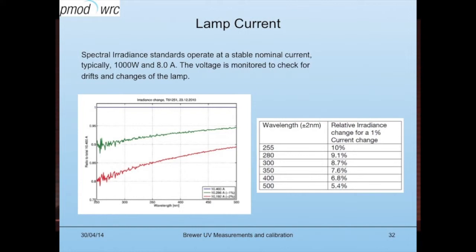For example, half of you have done the lamp calibration, and the company was really careful in adjusting or having you adjust the voltage for 12 volt, 0.000. And this is because the output of such a lamp is very sensitive to the power that it has. Now, usually when we operate lamps, we are controlling the current and not the voltage. Now, in the case of the 50-watt lamps, historically, it was much easier to adjust the voltage than trying to adjust the current. But basically, it comes down to the same thing. You are trying to keep constant power on the lamp.